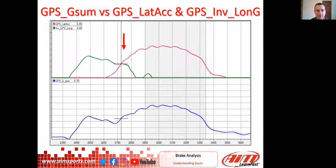Okay, next I want to begin to build that relationship for you of explaining what GPS GSUM is. So here we have GPS GSUM, lateral acceleration, and inverse long G all shown together. Your standard lat long are up here at the top, and your GSUM is down here at the bottom. If you notice, the shape of the curve seems very similar. However, where they differ is in this area of combination where they're both applied at the same time.